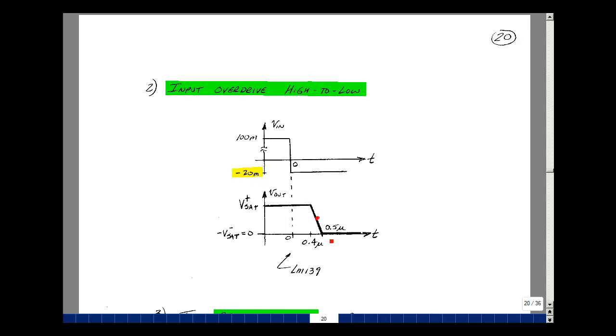This is because we're applying more voltage to the base collector diodes that causes more current to flow and discharge the capacitance of those particular diodes, and so it'll switch faster. You may notice here that these numbers are actually smaller than the ones on the previous page, and that's because we have PNP and NPN transistors, so the switching times won't be the same. NPNs switch faster than the PNPs because their basic carrier is an electron versus a hole.